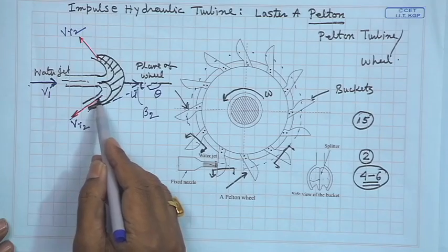But it is difficult to have a design of a fluid machine which under varying operating conditions will maintain that. Usually at its rated condition, it is designed in such a way that the angle of the relative velocity matches the blade angles at inlet and outlet. So, whenever in any problem we specify the blade angle at inlet and at outlet, it means that this is the angle the relative velocity makes. If the blade angle at inlet, with respect to the direction of the blade motion, is beta 1, that means this is the angle of the relative velocity with the direction of motion of the blade, like this. So, they should match each other.